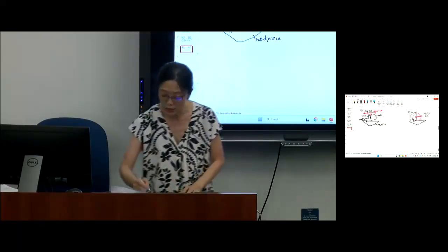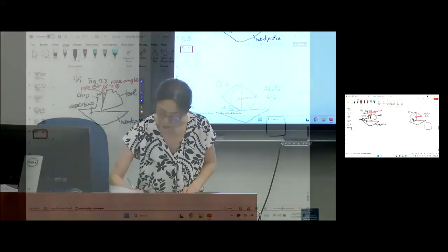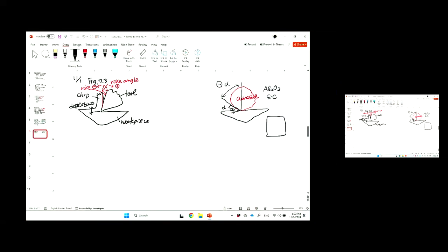But back to the sandpaper, right? Use like diamond or abrasive is there, right? Usually you don't see diamond sandpaper. It's very expensive. But on the backside, you see A and sharp, let's say 100, C sharp 100. You see it. So this A, that's aluminum oxide. C is silicon carbide. And then if you see this number, that's mesh, right?